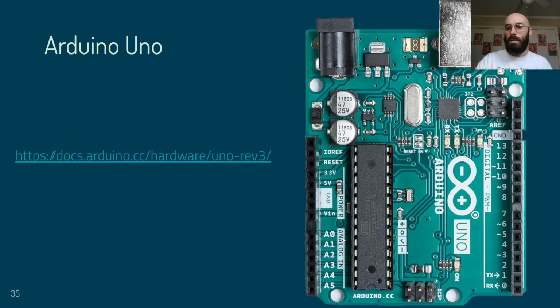And then on the ends here are these headers, we call them. These are different kind of sockets, again, where we can plug in little jumper wires and route it out to a circuit. So now, instead of controlling circuits just by wiring it up or using switches, we can actually route our circuits to the Arduino to have it drive different LEDs or read in information about whether or not a button is pressed or connect to different sensors and stuff like that. So that's what all of these different headers are for. These are connecting us to certain pins within the Arduino that we can then control.